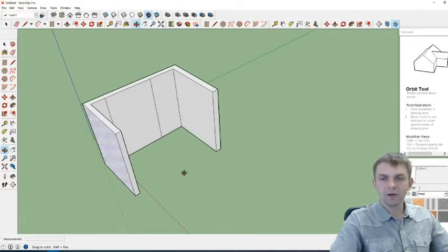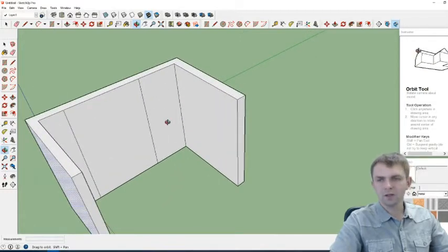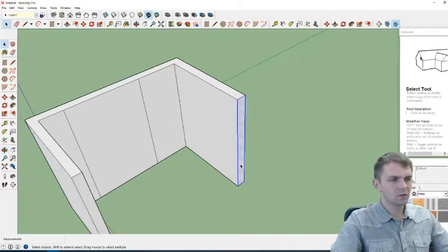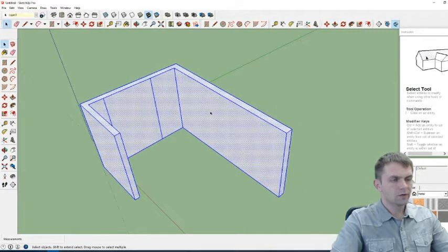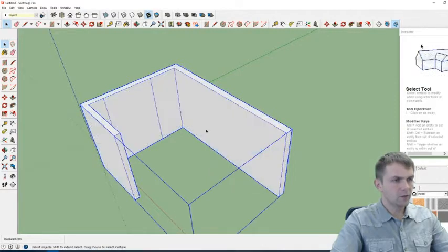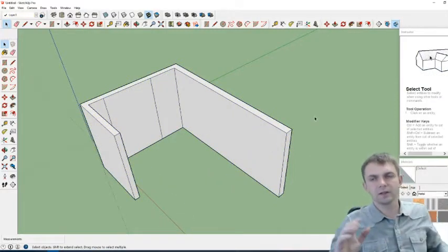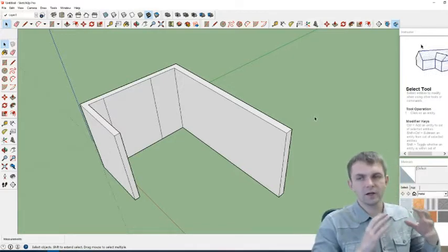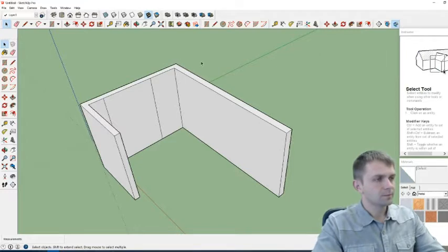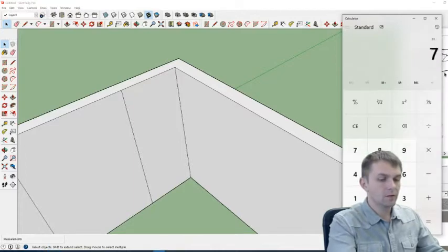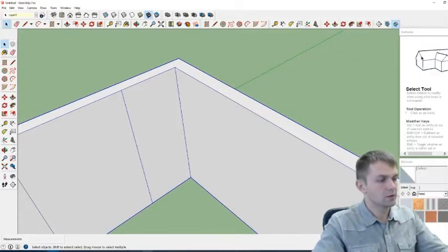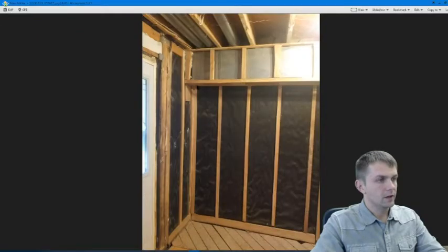What I love to do, and I really recommend for everybody, is to make everything in blocks. Then it's much easier to modify things. So this wall is basically just continuing this way. If I triple click on this and right click and make a group, now this is its own separate block, so nothing is going to happen to it. I cannot modify it, it's not going to stretch, it's basically frozen. And I'm going to add a bulkhead, and it's 96 minus 79, so it's a 17-inch bulkhead that we saw in the picture right here. So 17 inches down and it's 12 inches in.